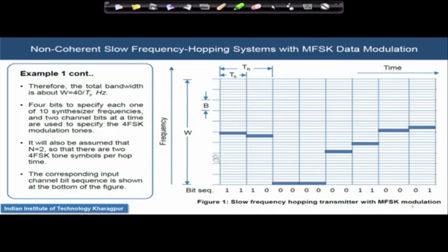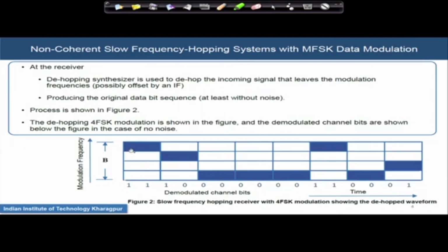So, now the hopping over the channel concept is over because it was de-hopped. Now we will concentrate only on the MFSK tones we are left with once the hopping pattern is turned off. First we had the highest frequency tone F4, then the tone F3, then the tone F0 simultaneously for 2 symbol periods. Like that, in the receiver we are getting the bits back.